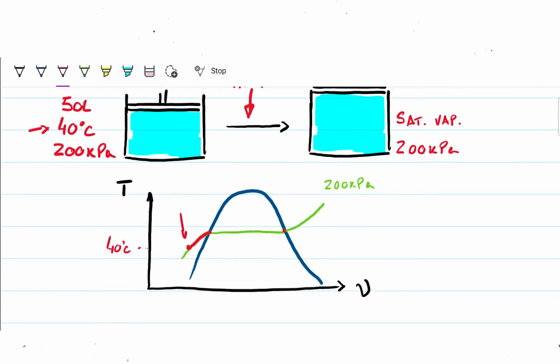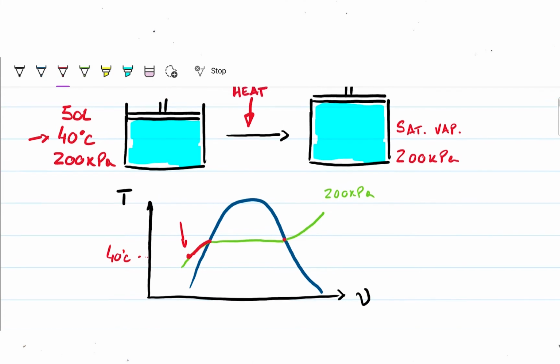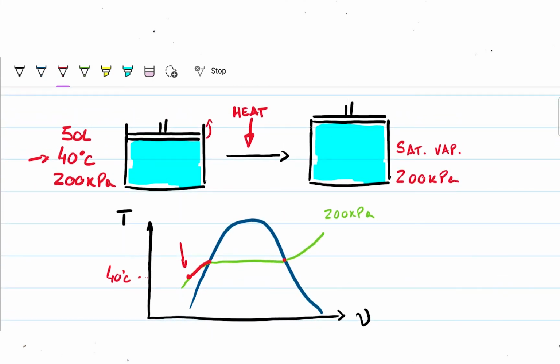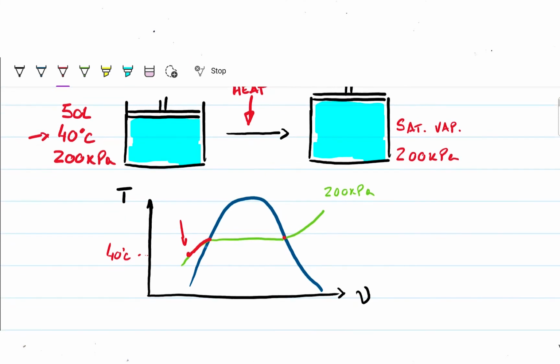Here it is. Okay, and I know that my temperature is going to be increasing as I'm giving heat to the system, right? My piston is going to be going upwards. That's why I drew the piston here higher than the other one, because it's a piston cylinder system. So as I'm giving heat, the pressure is not increasing because this guy can move freely, but my temperature will increase, and it will increase all the way until it reaches the saturated temperature, right? The temperature at which there is the saturated mixture for both the saturated liquid and saturated vapor, which has to be the same temperature. Note that once we go inside the dome, the temperature is not changing anymore.